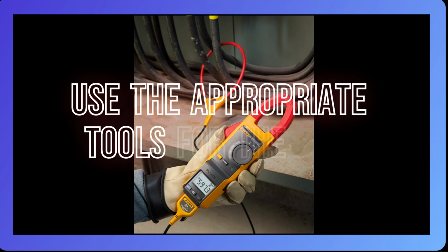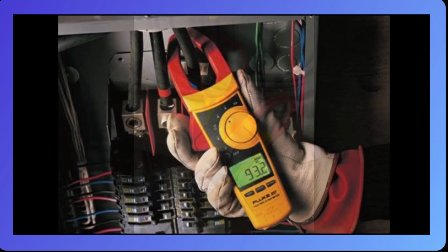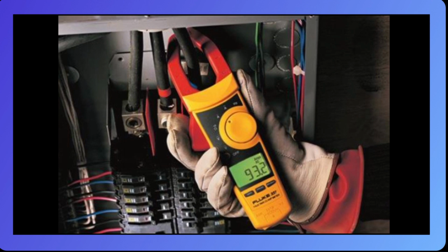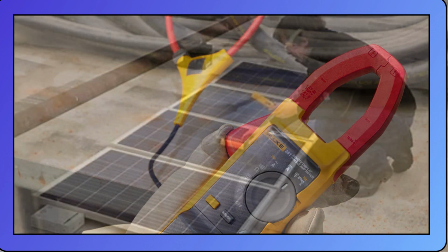Use the right equipment for the job. Use the proper tools for the job whether you are building or maintaining a PV system. A high-quality digital multimeter with an amp clamp or a clamp meter with voltage measurement capability is typically sufficient for the majority of operations involving the PV modules and their accompanying DC circuits.